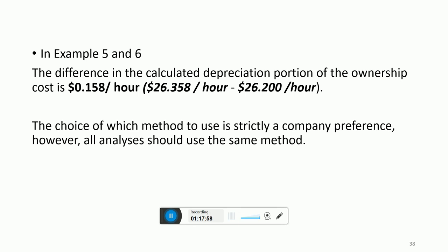Usually the equipment manager may look only at the high initial cash outflows associated with the purchase of a replacement machine, and consequently ignore the other cost factors involved. All cost factors must be examined when considering a replacement decision. So we have to consider all these costs, operating costs and ownership cost, before the replacement of equipment.